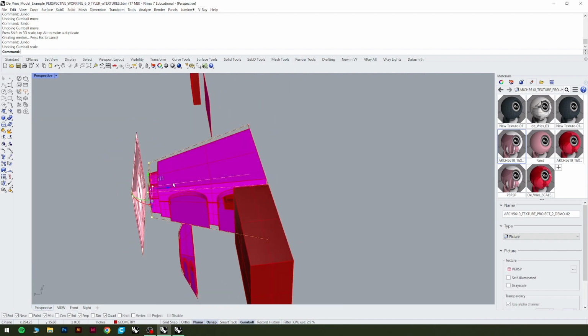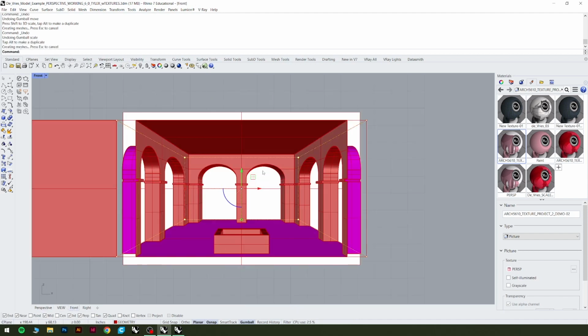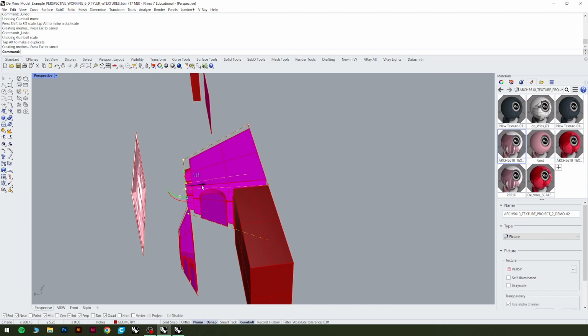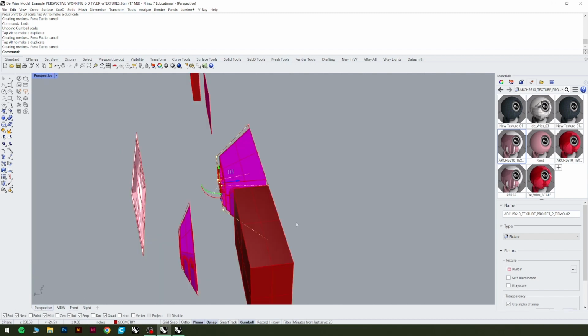So now I have that bounding box, right? So I need to create this thing at 4 inches deep. So with those 4 points still selected, rather than eyeballing it with the gumball, which you'll notice if I go back to front view, it's still the same. And I move it forward, I can go back to front view again, it's still the same, nothing has changed. It's all about that 2-dimensional projection of where these geometries are lining up with, and it's all about that scale. And it has nothing to do with the angle as it recedes into space.